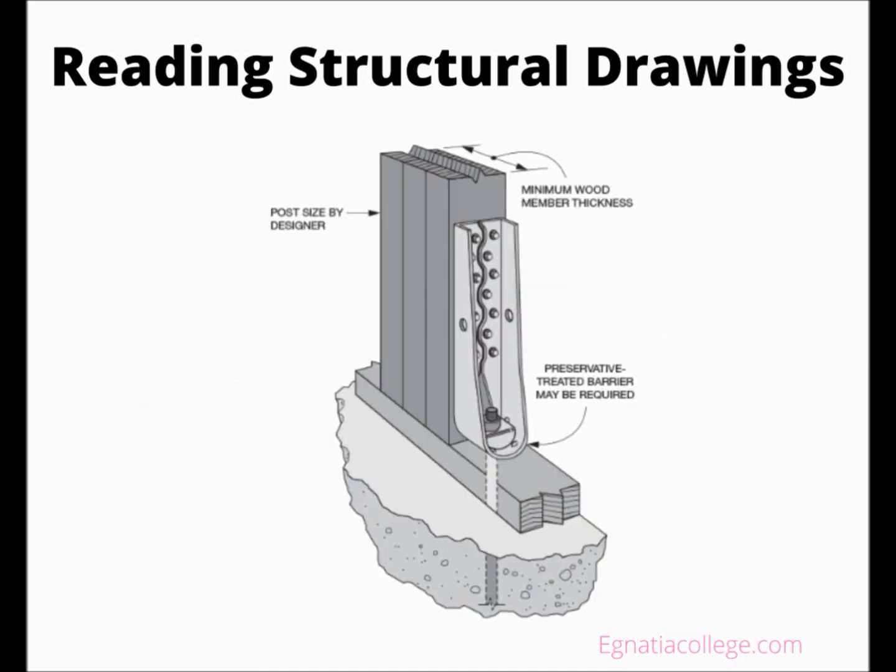Because steel has high tensile strength, steel rebar is added to the tension side of the slab, usually the bottom. This adds tension strength to the slab. To add even more strength to the slab on the Urban Quartz project, a process called post-tensioning is used in addition to using rebar. Post-tensioning involves the placement of a grid of plastic-coated cables in the concrete forms prior to concrete placement. Both ends of each cable penetrate the form and extend past the edge of the slab after concrete placement.